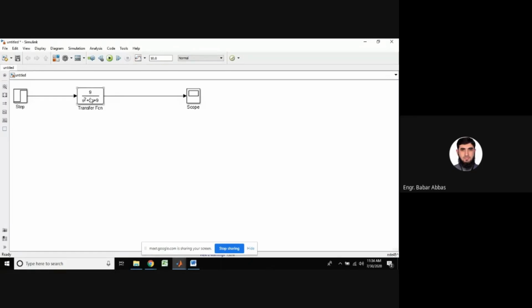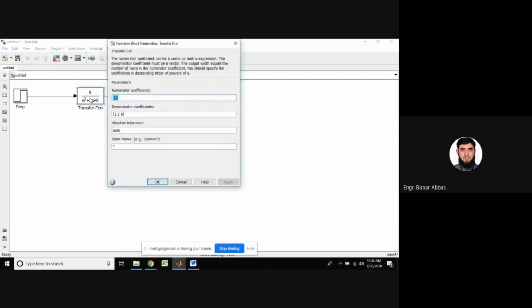Okay, so this is the transfer function for the antenna. The 3 blocks we have studied. The first block was the preamplifier and the power amplifier. The second block, you people know, was the motor and the associated load. And the third block was the differentiator.